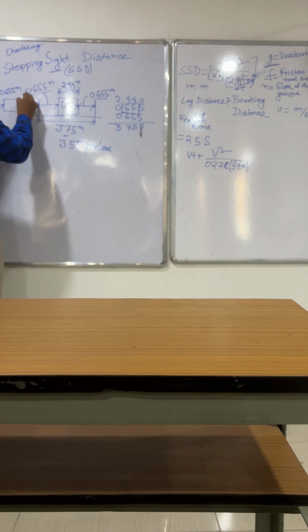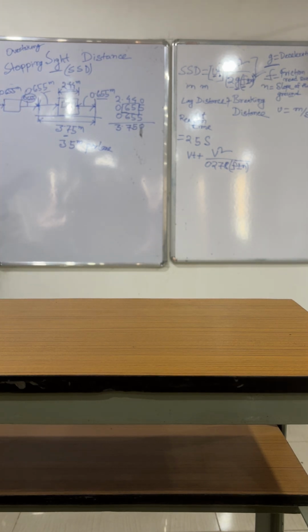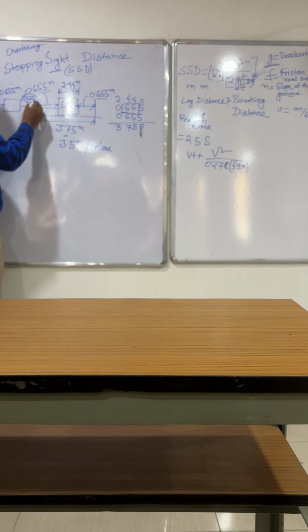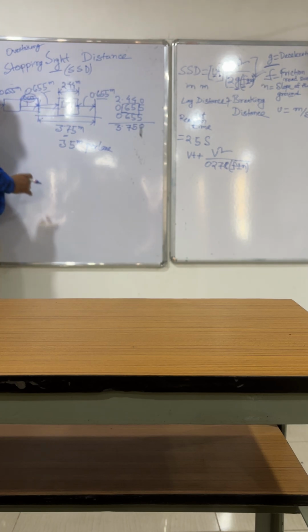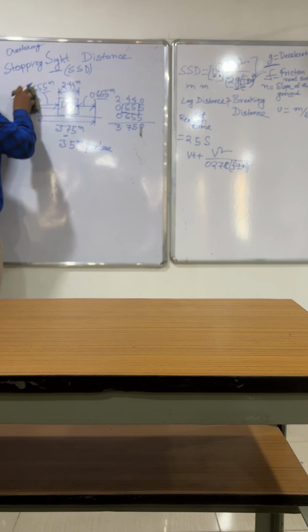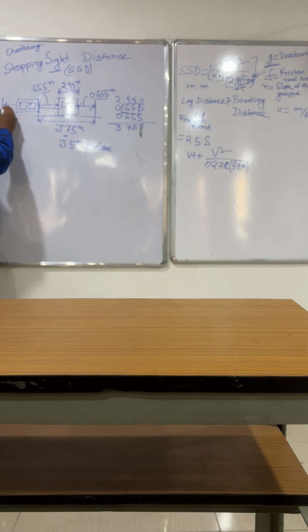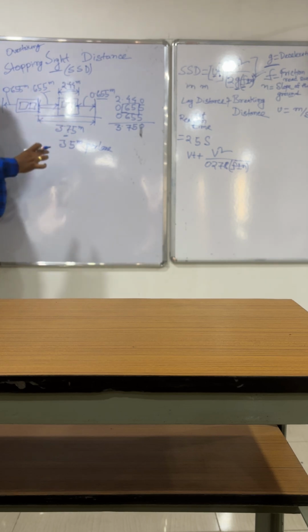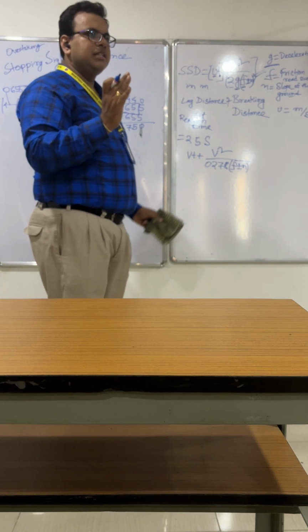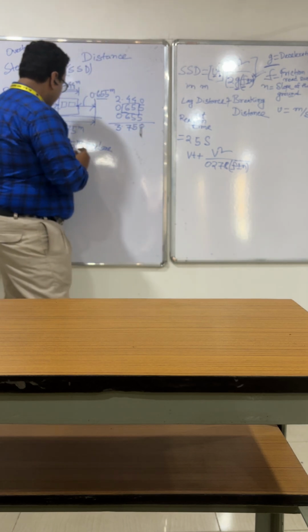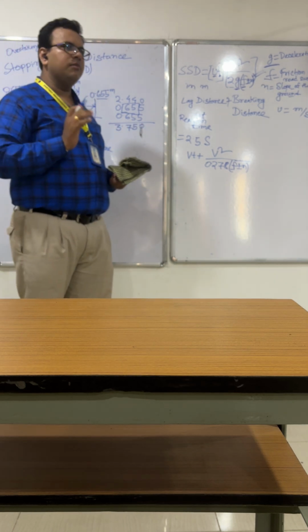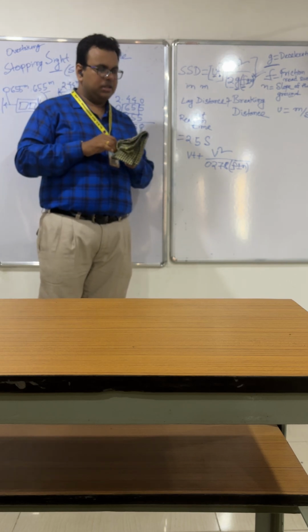Is there any need to take this one? No, because it is already here, so the vehicle can also move here. So your vehicle may come in this position. This could be your vehicle. Then there might be another space of 0.655 meter. So an additional lane reduces your space. Accordingly, people can take 3.5 meter per lane for additional lanes.